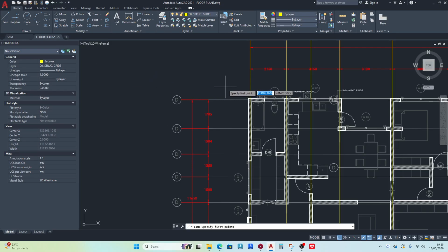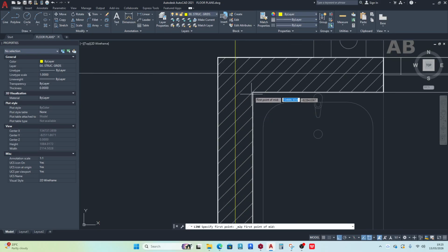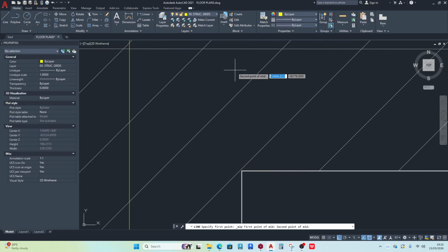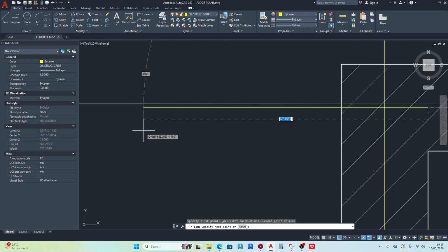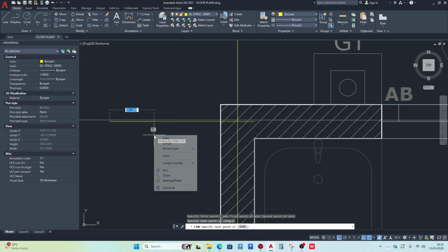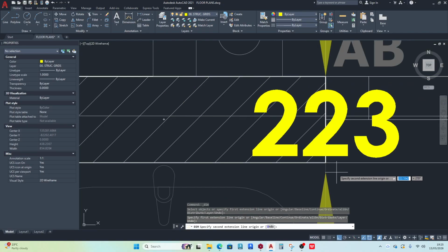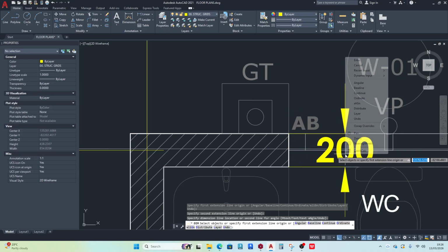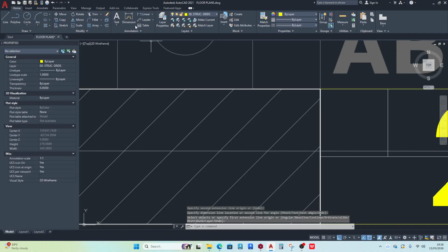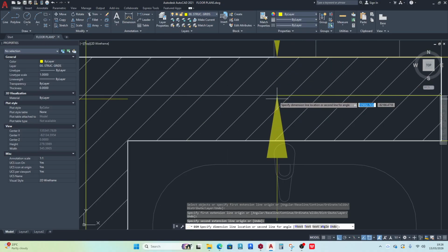Select the line again. Hold down Shift, right click, choose mid between 2 points, and I want the middle of that and that. So my mid is different from the architect's mid. Let's see. It's claiming these are 200. Okay. What about from here to here? 92.